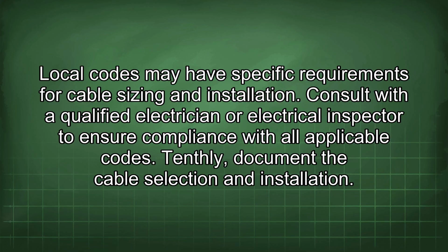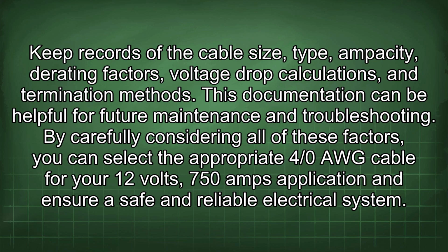Tenthly, document the cable selection and installation. Keep records of the cable size, type, ampacity, derating factors, voltage drop calculations, and termination methods. This documentation can be helpful for future maintenance and troubleshooting.